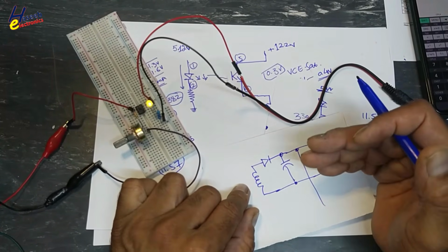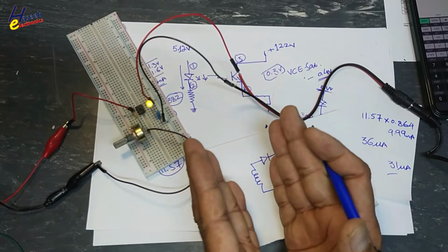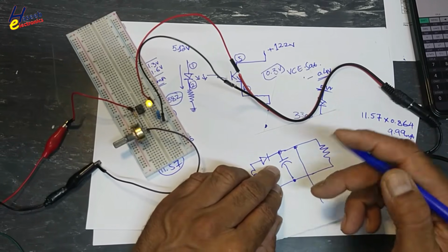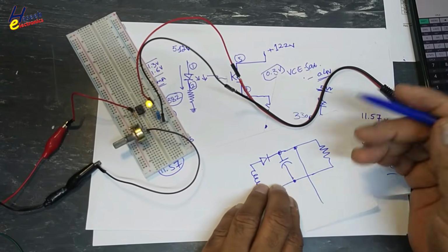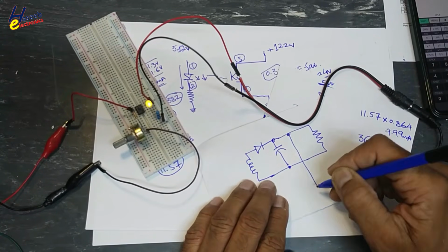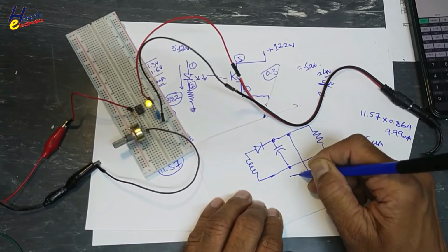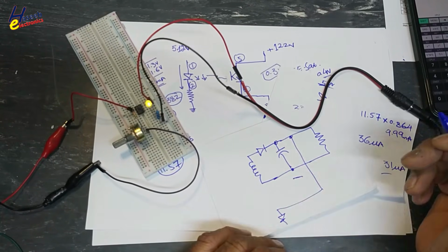In half cycle, when it will switch, it will store voltage in the magnetic core. Then it will transfer voltage in this capacitor. This capacitor will run load. When it will run load, the voltage will decrease. When voltage will decrease here, same will reach to optocoupler.